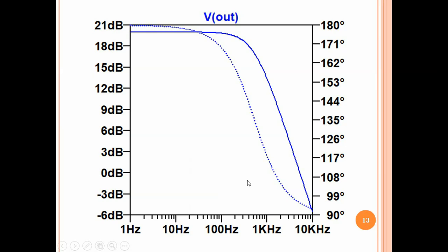All right. This is the actual frequency response of the same circuit for some given value, which I obtained in a circuit simulation. It is flat at low frequencies. It drops at 20 dB per decade at high frequency. In between, there is continuity. The approximate Bode plot would go flat up to the corner frequency and then start dropping. By the way, the dashed line is the phase plot. The solid line refers to the left axis, which is in dB. The dotted line refers to the right axis, which is the phase in degrees. But as I said, this course will not look at the phase plot at all.